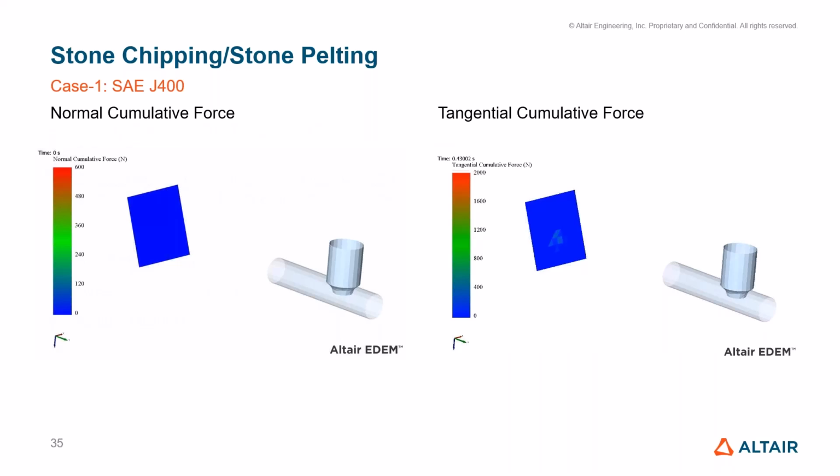As I mentioned, if we calibrate and use the appropriate Oka wear or Archard wear, it gives us the amount of material removed. If you are not able to perform a calibration for the wear, then we can still use the relative wear model to predict the wear region.